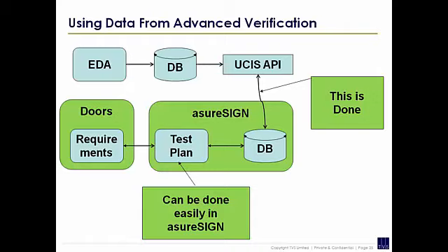I've got more experience on software than hardware. A lot of the software tools would allow you to do on-target coverage analysis, for example. But on-target, these techniques really only apply in simulation, so it's very difficult to do that on-target. Are you able to do it at speed, or do you do it reduced? Most of Aldec, Mentor, and us will all do it via simulation, which is simulation speed rather than at speed. There are ways of doing functional coverage on FPGA, and you can do it at speed there. But most of these techniques will only apply in simulation and not at speed. So there is a problem there, definitely, if you're trying to do all your verification at speed.